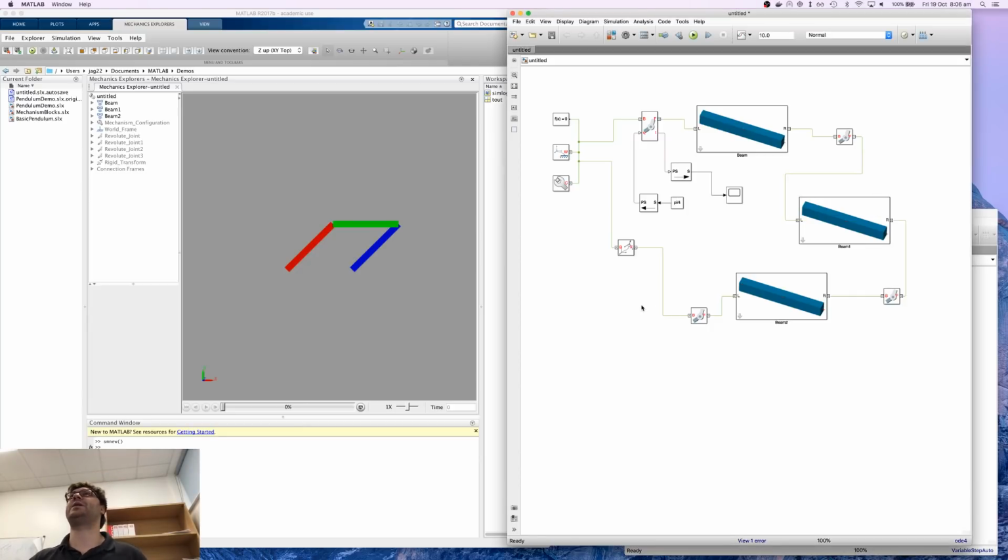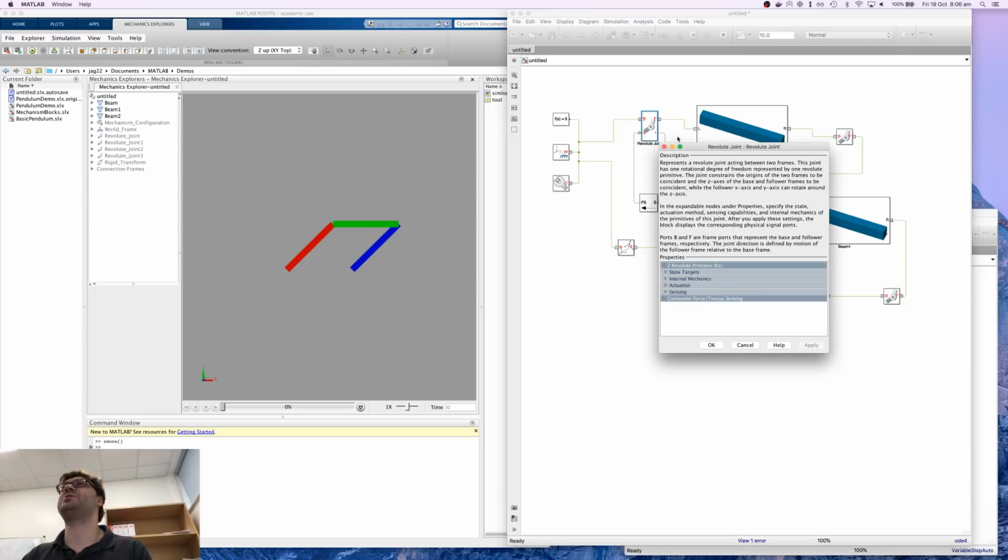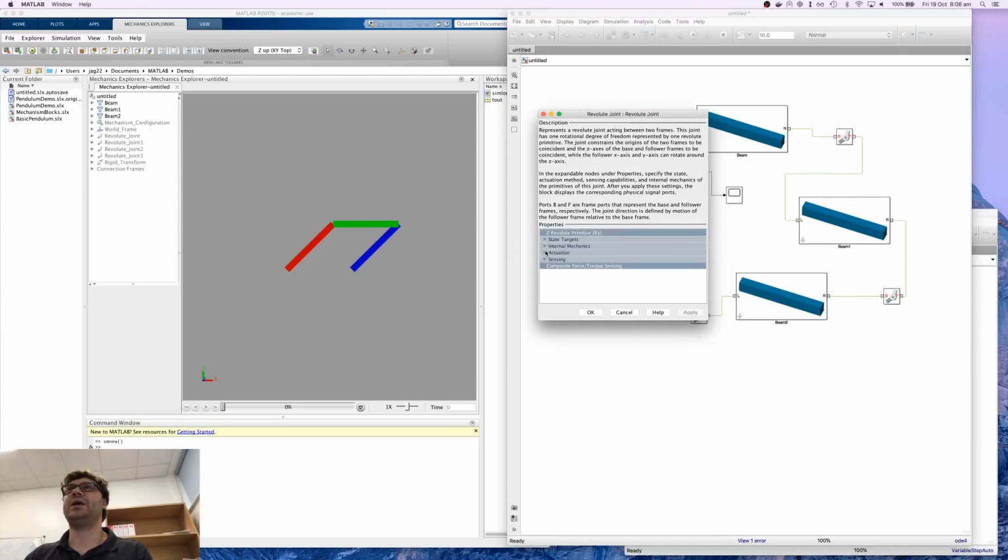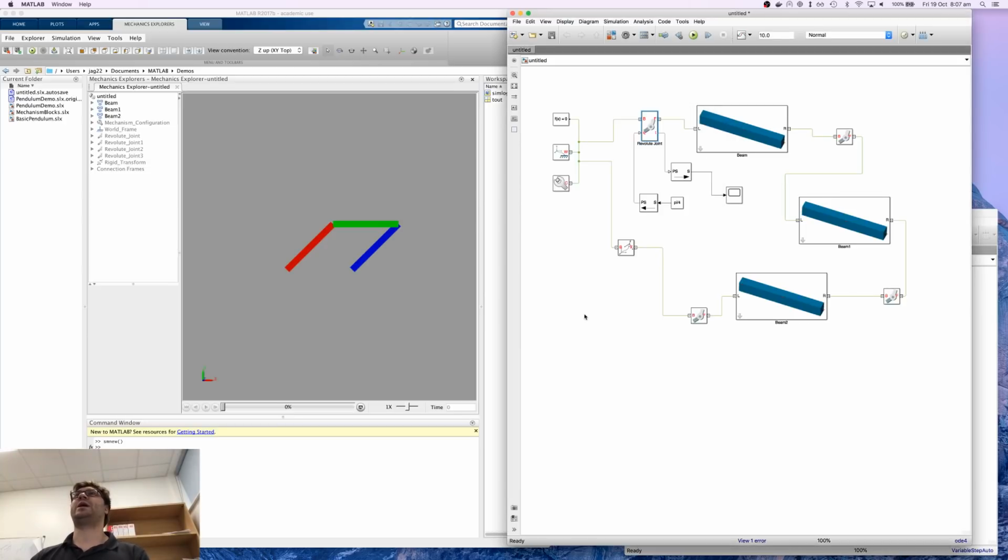Aha, sorry about that. I just had to double check on my other model. The actuation, of course, torque is none, is actually going to be automatically computed. So we wanted to switch that round. We're going to get the computer to compute that for us. Otherwise, we're saying there's no torque, but we want to fix it to position, and it's thrown an error saying we can't resolve that condition. So if we click OK now,